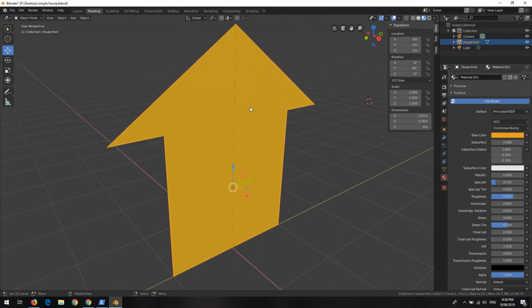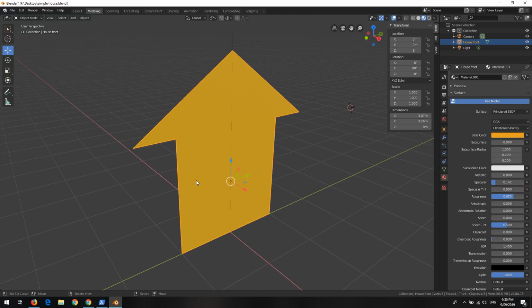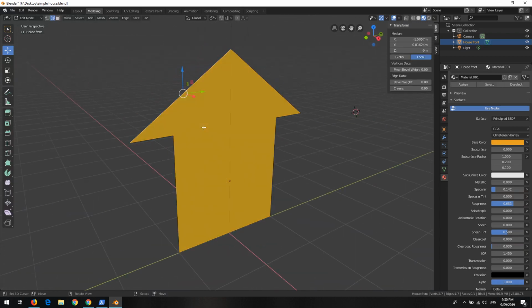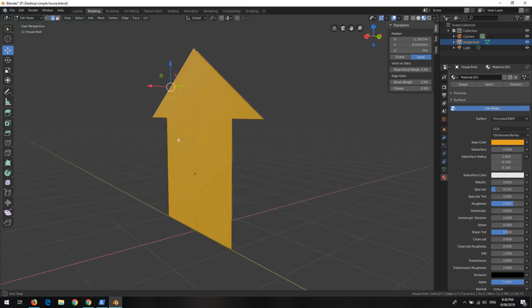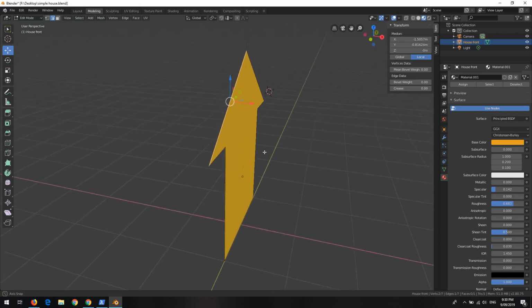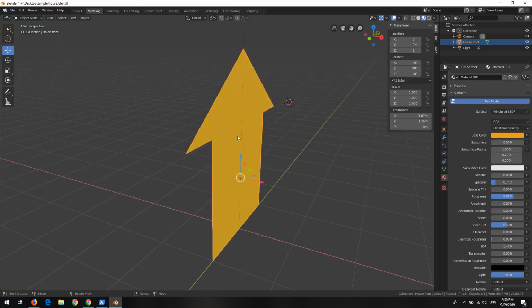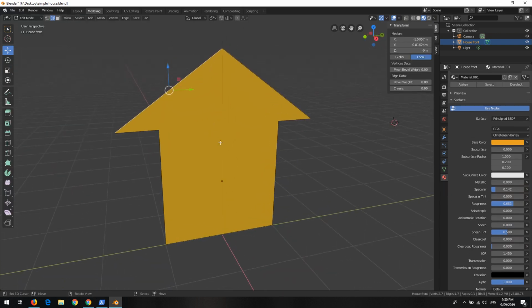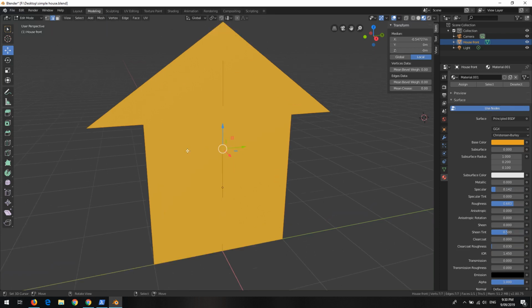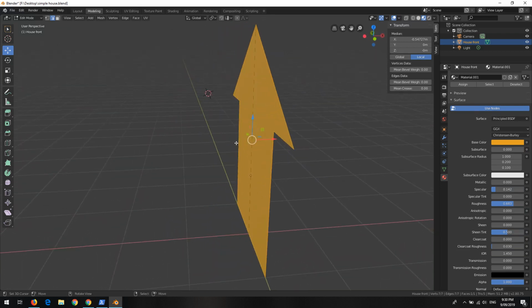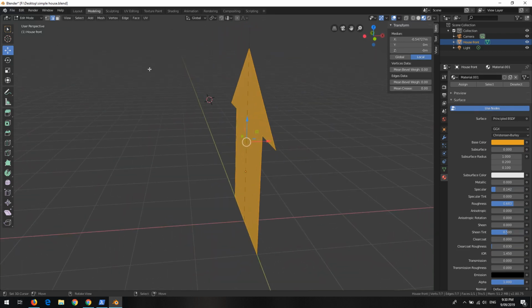Okay, let's go back. Let's do some further editing, and let's create the roof. So from the side, really simple. Shall we apply a thickness to this? We can do this by pressing A. If you press A one time, it selects all. So it's now selecting all the edges, as we have edge selection mode. Now pressing E again, now extrude, like we extruded a single edge. Now extruding all the edges, creating a solid.